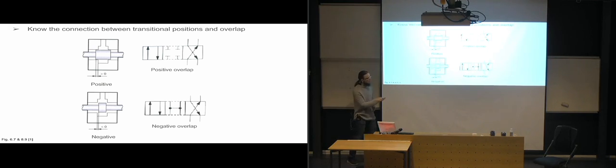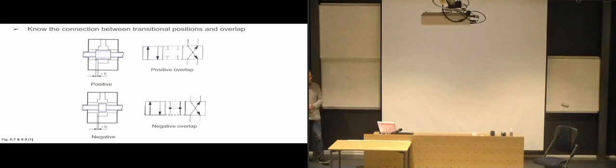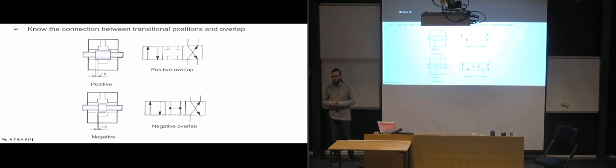So depending on how quickly you're moving the slide over to the opposite switching position, you can potentially lose quite a lot of pressure. If it's a hand lever and you're just slowly pushing it over, then you're going to lose quite a lot of pressure before it hits the other switching position. If it's a solenoid, we're talking about milliseconds before it hits the other side, so you're probably not even going to be able to read off a pressure difference on a pressure gauge. But with a hand lever and moving it slowly, you would really see the effects of this.